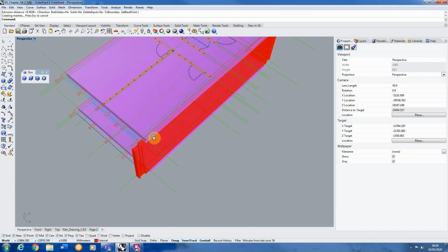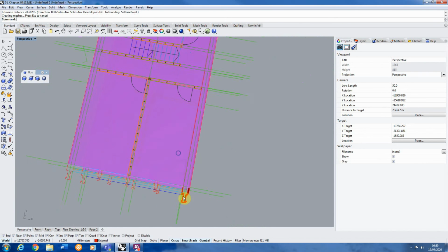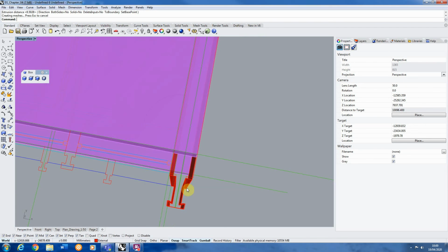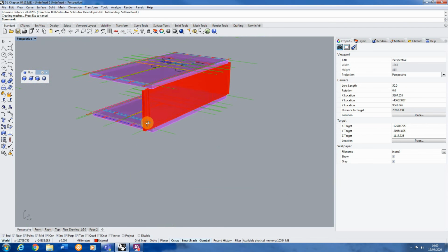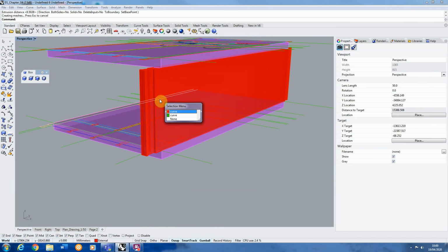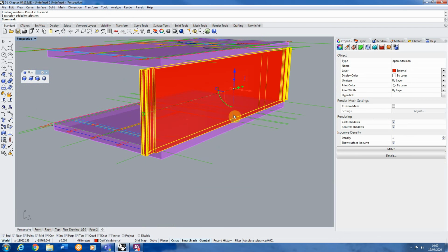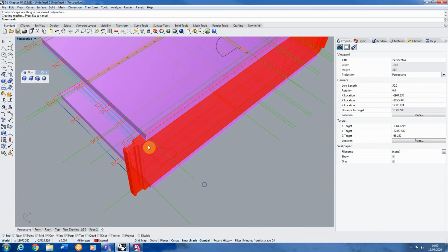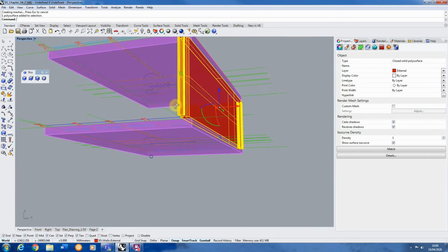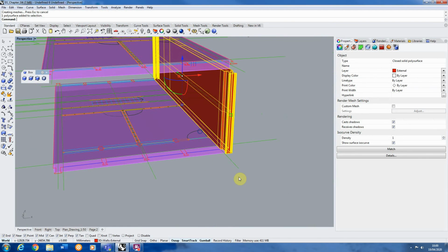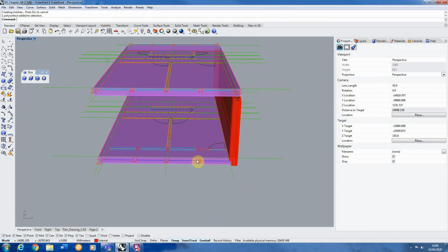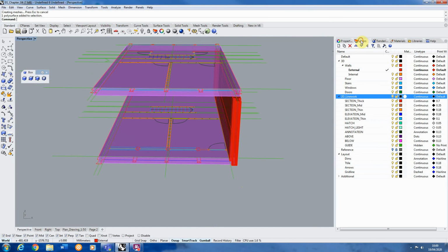So if you've done it like I have now, and you see it's still got that hole, top and bottom, we can do what we call capping solid objects. So if I select the object and type in cap, that then adds a top and a bottom, making it a solid object. Now we can actually do that to all of our curves at the same time.